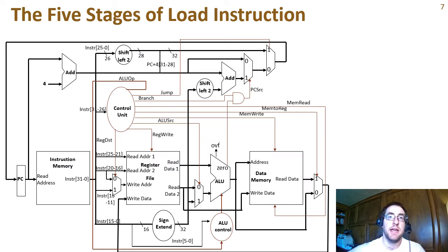So back to our single cycle MIPS processor design. To pipeline instructions, we have to identify the stages of their execution and divide them up into roughly even chunks of time that we can split the instruction cycle into.